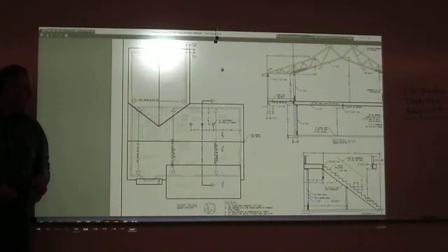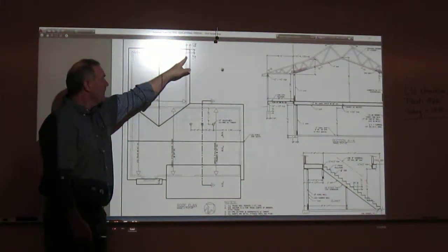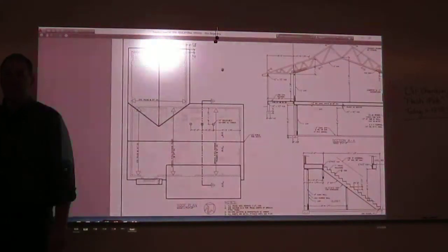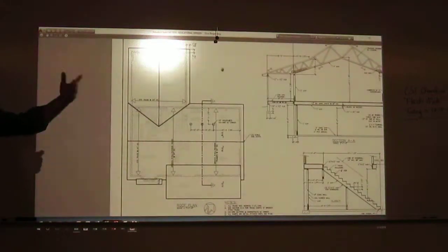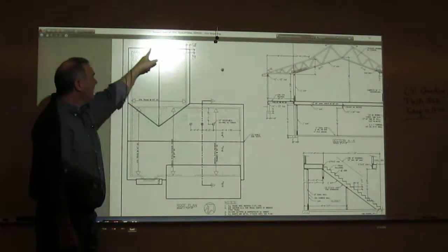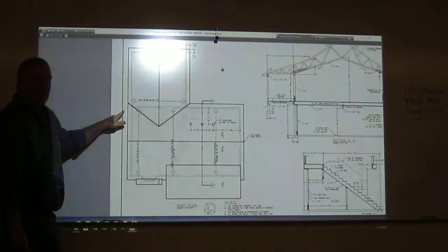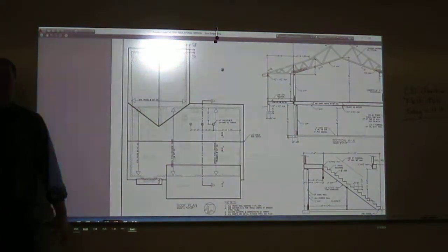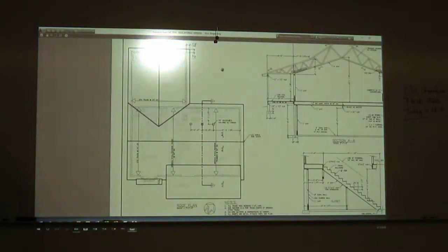Okay. Now, our footprint, this hidden line, is going to bear all our trusses, and that should all have been in there. We did all that together. That's just copying the outside of your main floor plan over, and then drawing your eaves, where we went pretty standard, 18 inches all the way around, right? So, should we talk about framing notes and how we're going to put those on? Because in essence, we need to do that.